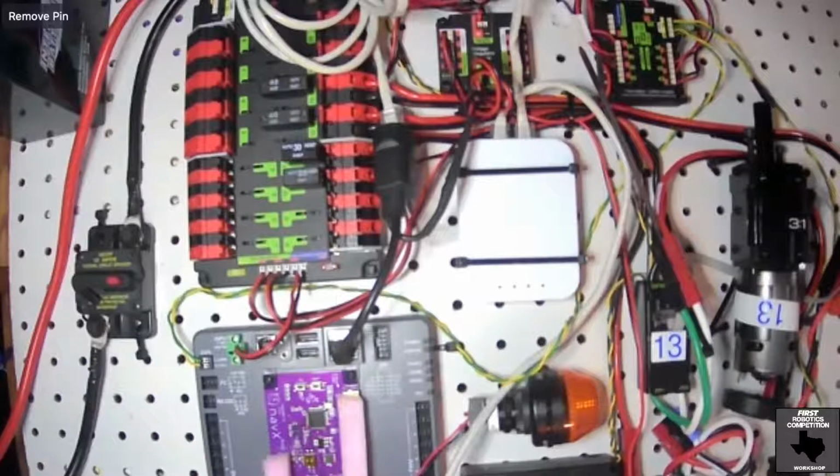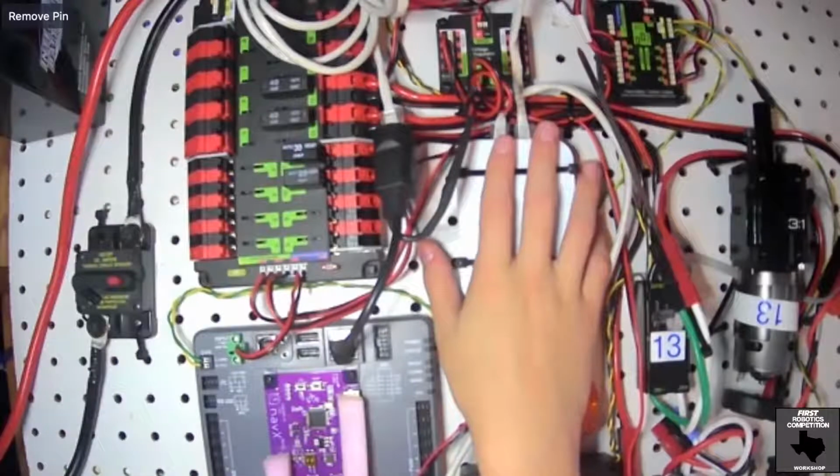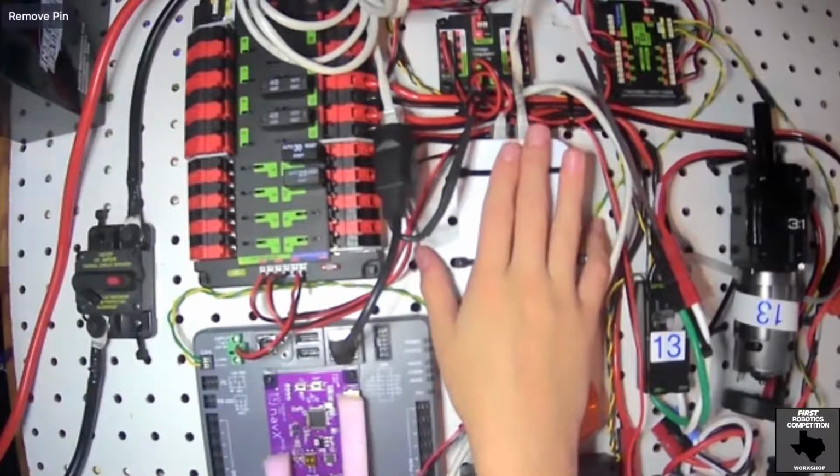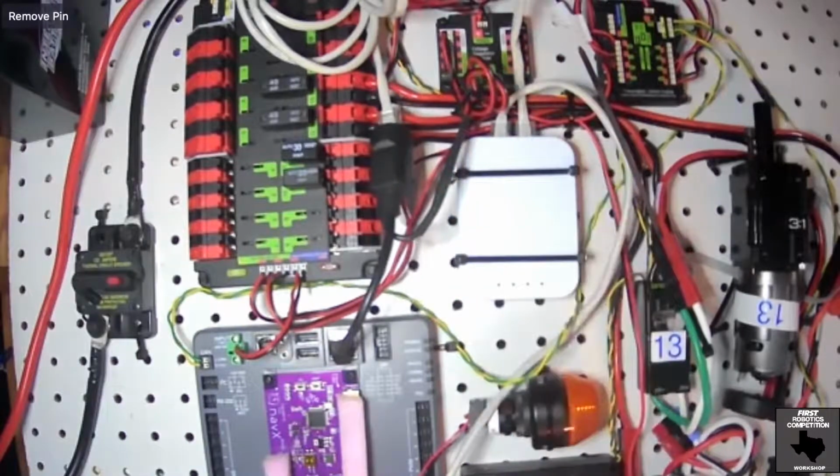And then Dylan was talking about hot glue. You have to be very careful with hot glue. I specifically only use hot glue on the radio. Hot glue can come off, but it's more of a permanent thing, so just be careful where you're putting it. You don't really want it anywhere where there's going to be exposed wire. We typically have only ever used it, in my memory, on Ethernet ports and barrel connectors.